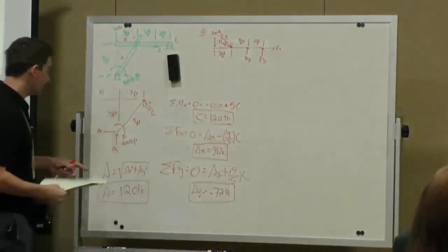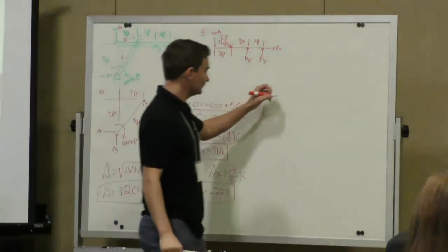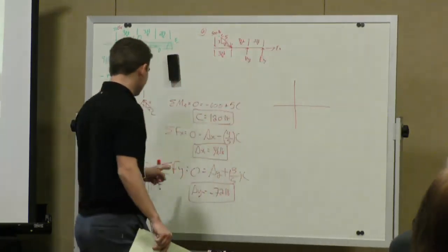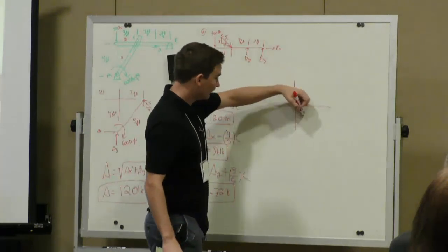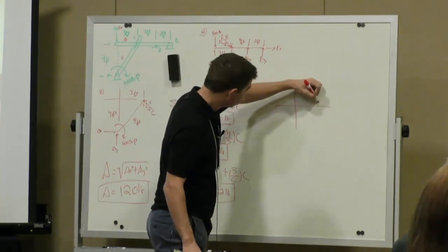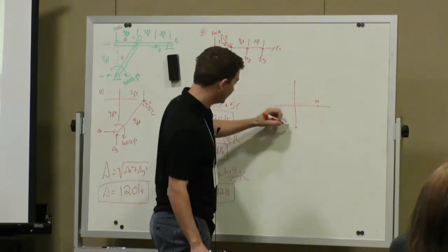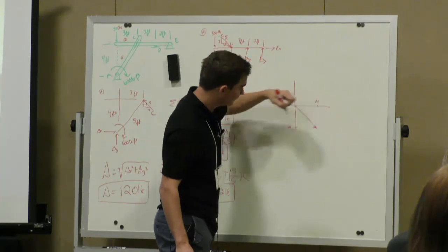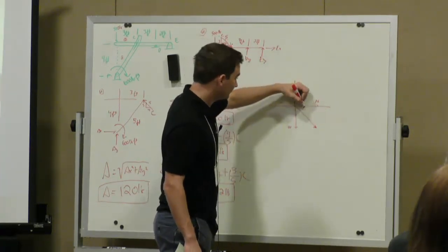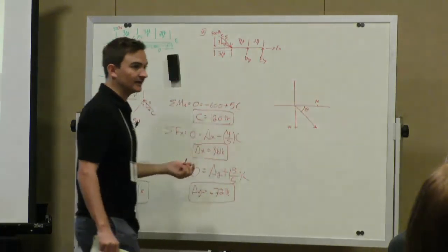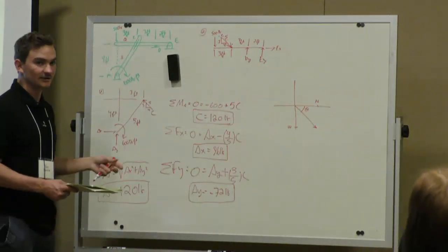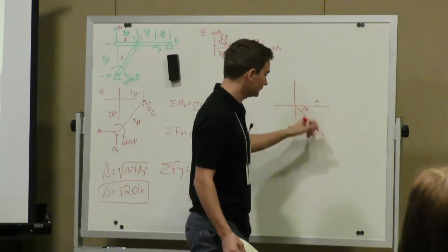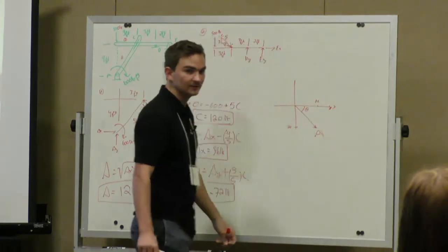No? And then say the question asked you, so let me just draw this out. I haven't calculated this, but we have AX acting in the positive direction, AY in the negative direction. So AX is, say, 96 pounds. This is negative 72. So your resultant force is acting this way. If I asked you to find theta, how would you find theta? I may say, what is the direction or the angle this resultant force is acting from the positive x-axis? So how would you find theta?